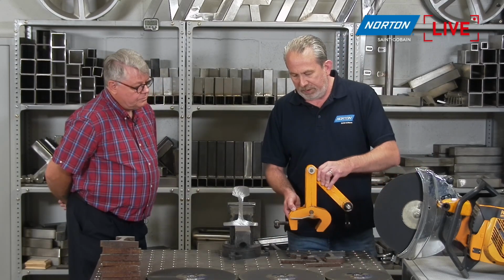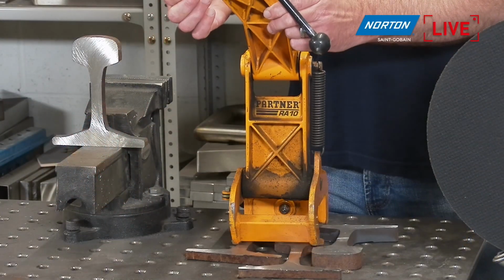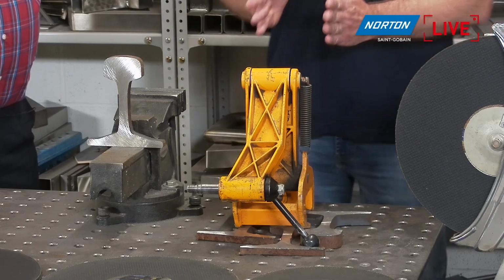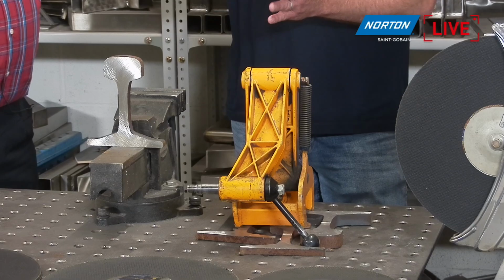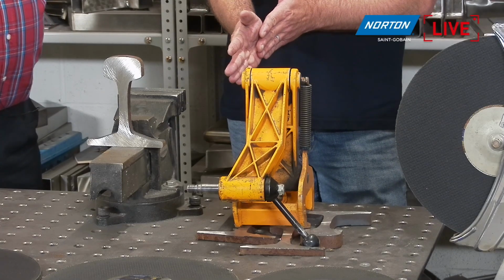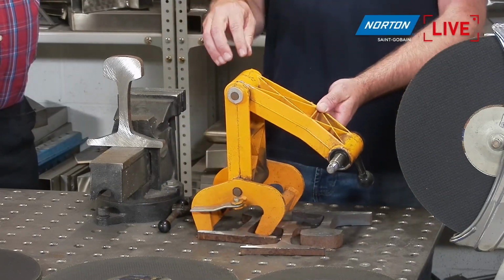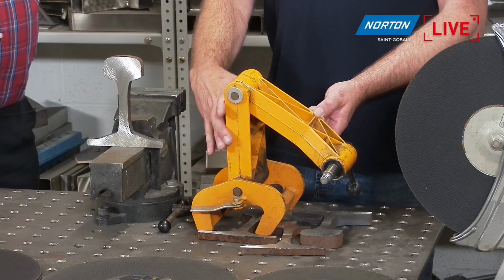Now, this clamp actually clamps onto the rail. We fix the machine onto this spindle here and tighten it on, and that holds the machine in a purely fixed 90-degree angle to the track. Or no, it's not. It's a 180, isn't it? So we're right in line with the track, parallel with the track itself. So you can see how that works. This controls the saw and makes sure you get a dead straight cut through your material.